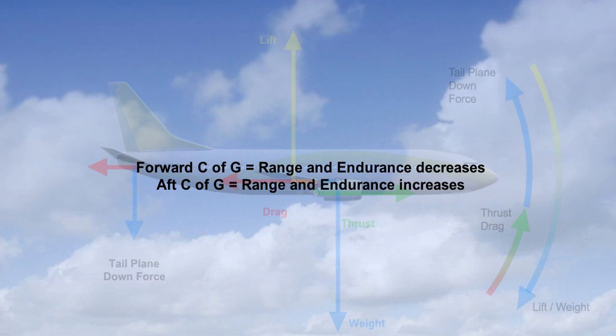Remember that, before you fly, when carrying out a weight and balance check, also ensure that the centre of gravity is still within the limits published in the aircraft manual. Be extra careful when handling data produced by countries whose units of measurement are different to those you are used to.